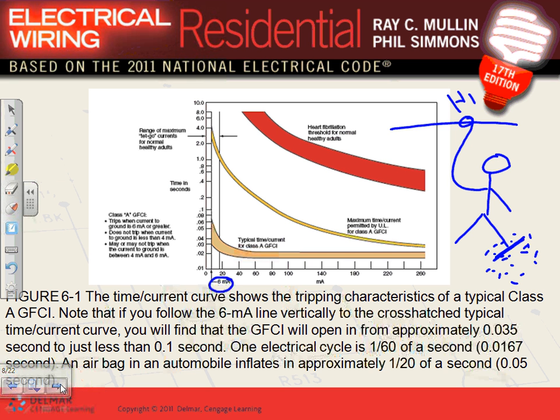If you have a circuit breaker like this and you don't have a GFCI, a circuit breaker will trip, but not before you go to the second life. You see the difference? It will trip eventually, but you will be dead by the time it trips. You wouldn't know that it tripped. People will pick you up, probably they would know. Can you see the advantage of why GFCI is a big deal? Put GFCI in the system.